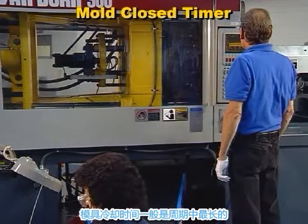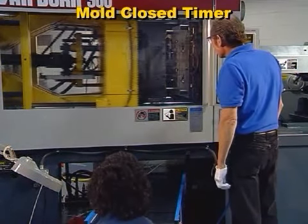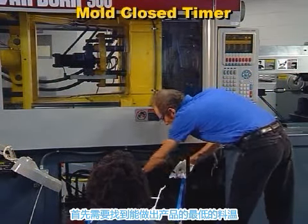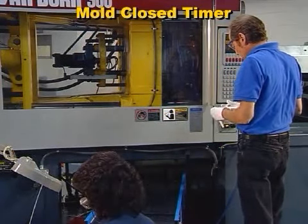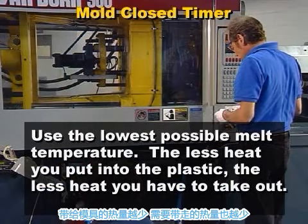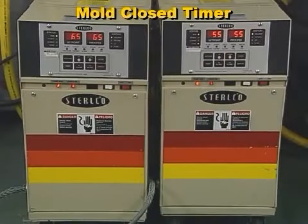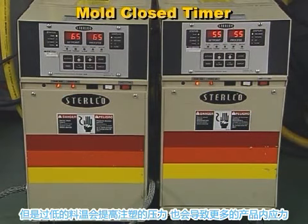The mold closed, or cooling time, is usually the longest phase of the molding cycle. Cooling time is minimized by using good molding techniques. First, you should experiment to determine the lowest melt temperature that will make good parts. The less heat you put in the plastic, the less heat you have to take out. Lower mold temperatures also help reduce cooling time. But low mold temperatures increase the amount of injection pressure required to fill the mold and may also cause undesirable part properties like stress.